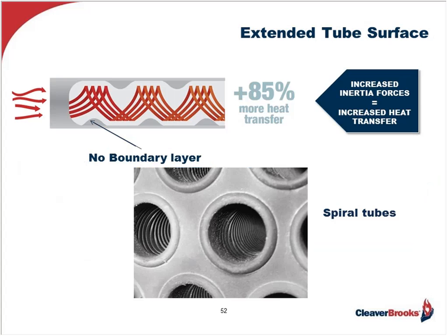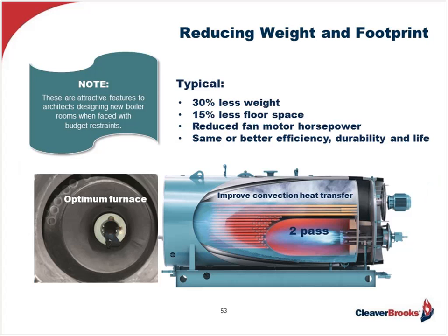Now, in the optimized fire tube boiler design today, the plain tubes are replaced with highly engineered spiral tubes, wherein the number and spacing of the spirals and their angle to depth are closely analyzed. This is not only for the heat transfer purpose, but for pressure drop and tube life purposes as well. So, in the end, we are left with a totally optimized tube, which totally breaks up the laminar flow, greatly increases the heat transfer rate by up to 85% while delivering higher Reynolds numbers and heat transfer coefficients.